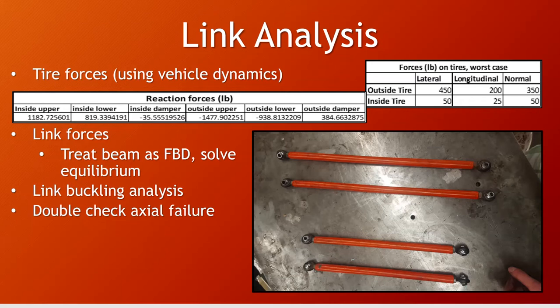Because the links are long, slender, and are pinned with bolts at the beam and chassis side, they may only transmit loads axially. This is only so long as the suspension remains in the intended range of travel. If the suspension were to reach an unanticipated amount of travel, for example, the links could then see loads other than axial. It is for this reason the suspension is designed so that the beam and links will not kink and incur a catastrophic failure scenario.